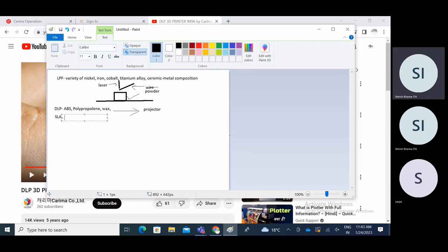It uses a laser to draw each layer of the model into a photopolymer, using resin and curing it one layer at a time. A beam of UV light in the form of a laser is projected onto a point in the resin, causing it to react and become solid. So layer by layer the object will be created in stereolithography, SLA.